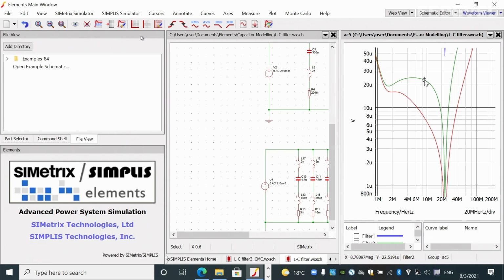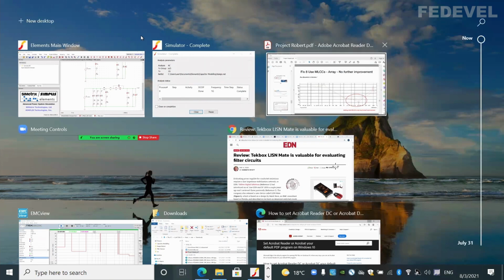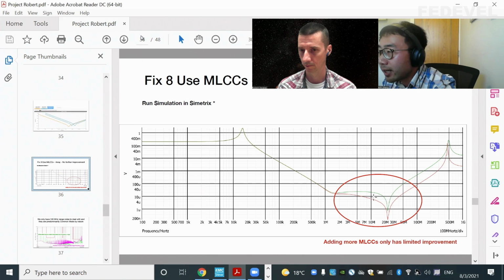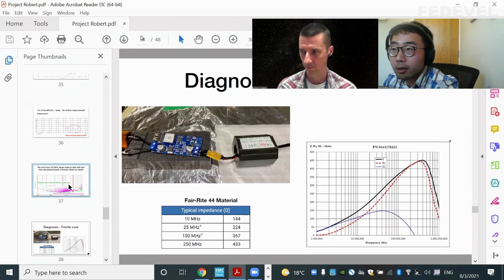If you look at this, we're talking about 20 micro, 5 micro. It's 4 times, which is less than a few dB. So this improvement, what it translates into the measurement is that we probably won't be able to see any change in the setup we measure, because it's only really a few dB difference. Whereas, previously, if you look at this LC filter we talked about, it's 40 dB at least.